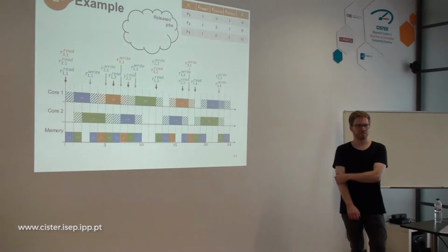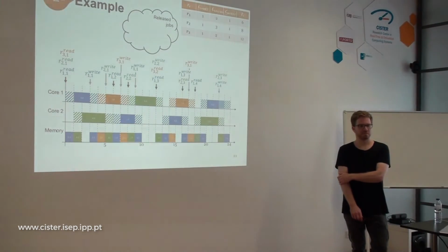So we have a kind of prefetch mechanism on just 4 banks. Then the runnables, before running, will take the shared labels in the shared bank, and we make sure that their code is already ready in some other bank, so that they don't communicate with the off-chip memory.